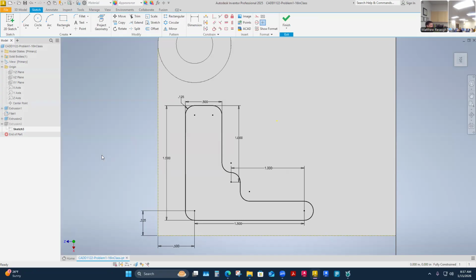I will say that is something that I tend to break away from in my CAD type sketching, in my Inventor sketching. I will occasionally draw a construction line here or there, and you'll see me do it in the next chapter 2 exercise. But a lot of times I won't, because I will use constraints rather than construction lines. I will use dimensional and geometric constraints instead. I will just lock in the dimension that those have to be. And so yeah, it's all connected.